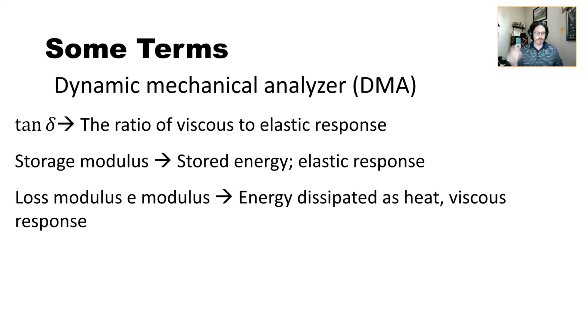Anyway, let me carry on before I digress too much into some story. So tan delta is the ratio of viscous to elastic response. The storage modulus is the stored energy, so that's the elastic response. The loss modulus is the energy dissipated as heat, and that's the viscous response. Later on, I'll show you an example of different dampening materials.